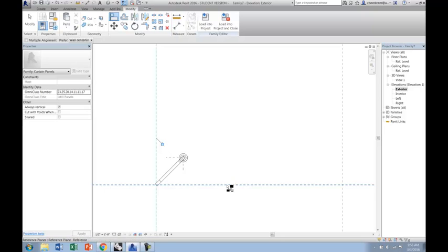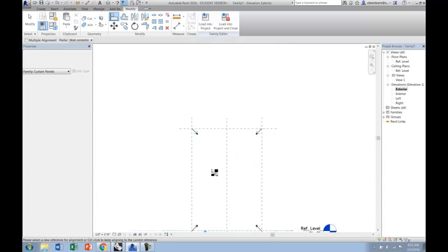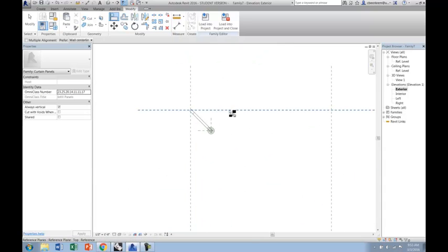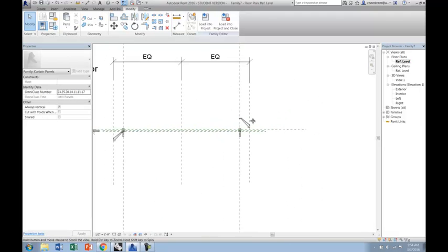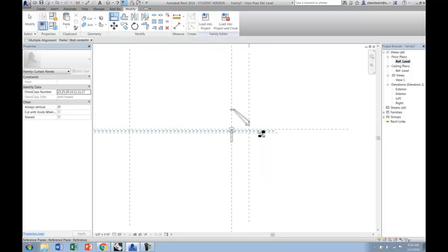So I'm going to select the reference plane and then find the reference line there for the arm itself. And again here, reference plane, and then this little line when I hold over it, it says it's a generic model arm reference. So there, and then that thick blue line to get the arm reference piece, and then back in plane we'll need to snap them onto the face, the appropriate face. So this plane to that guy, and lock, and this plane to that guy, and lock.